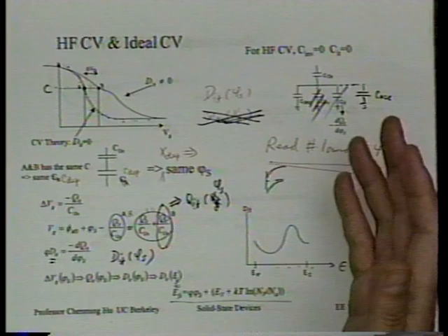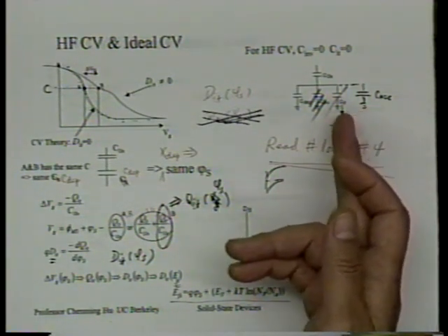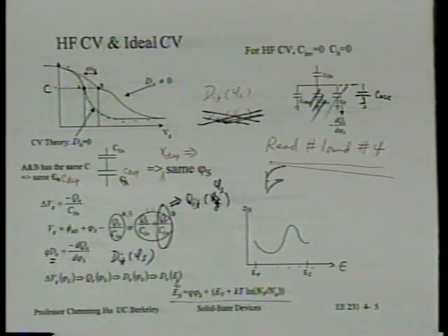I explained the fact that the interface charge does not respond to changes in phi s by the fact that there is a physical separation between the traps and the semiconductor, not by the lack of electrons in the semiconductor.